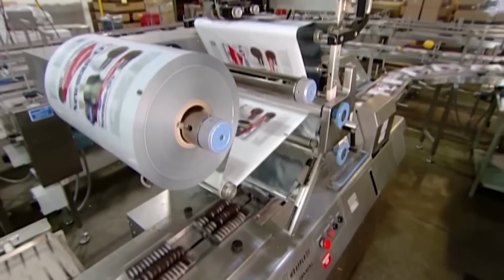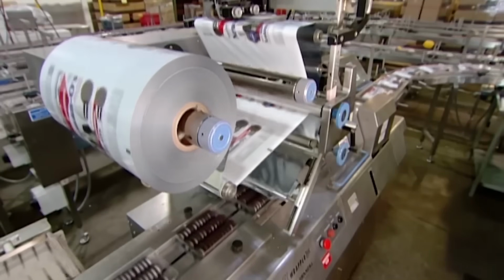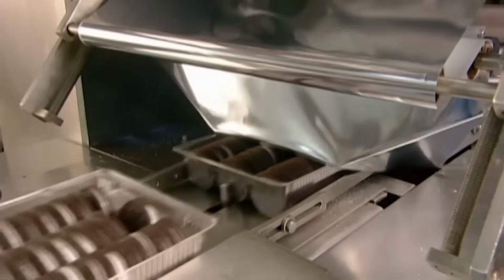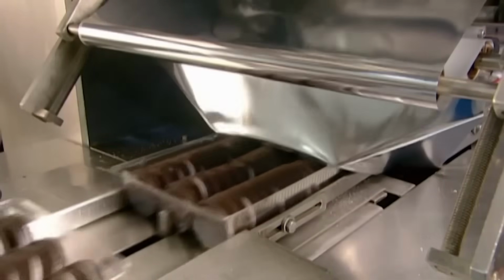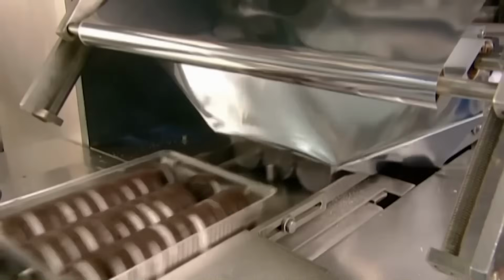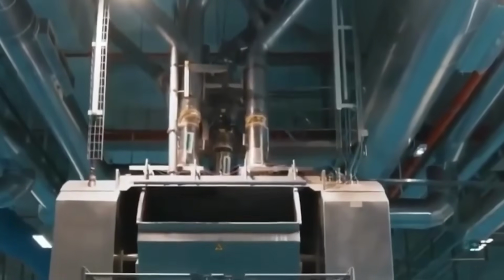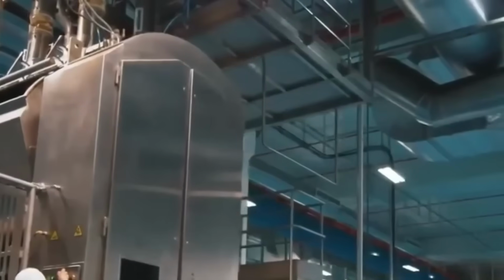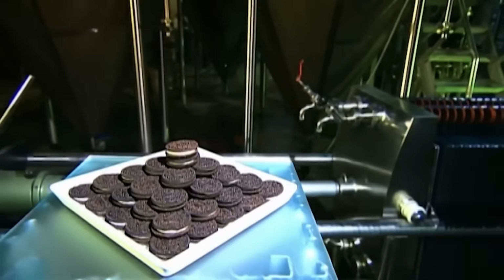Once sealed, packages are conveyed to automated case packers. Here, robotic arms load the wrapped units into corrugated cardboard cartons, which are then glued or taped shut. These cartons are palletized according to preset patterns that optimize load stability and cube efficiency for shipping. Pallets are wrapped with stretch film, labeled with shipping barcodes and inventory data, and routed to the warehouse staging area.